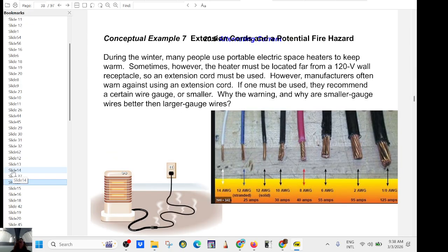You have to be careful. Well, you don't have to worry in Florida, but in New York, my students' dorms were cold, so they would buy those cheap heaters, but the cord is never long enough. So they get an extension cord at the dollar store, but in that case you have to be very careful. You have to read the maximum current it can take. Because if you get a thinner wire, the cross section is smaller, so you increase the resistance of that wire, and more energy will be lost to heat.